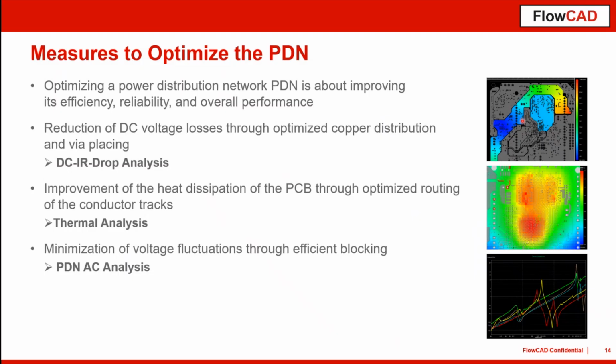And we must make sure that the voltage at the receiver side, or its receiver ICs, still meets the voltage requirements. Furthermore, we also have to achieve a stable power distribution network without any resonances, where all these decoupling capacitors have to be analyzed. And that can now be done with the AC analysis that I will show you later on. And finally, we also have the possibility to do some minor, first-order thermal analysis, as shown here, that I will also present a little bit later on.